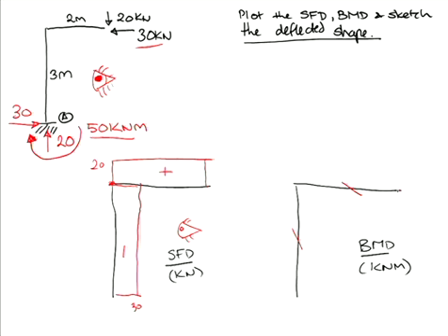So what's the bending moment at the cantilever tip? Everyone, together, 0. What's the bending moment at the fixed support? What's the absolute value there? 50, okay? You know it's equal to the bending moment in the beam. If I now draw a small free body diagram here, I'm saying the moment in my reaction moment is 50 clockwise. So to get equilibrium, the moment in my beam would be an equal and opposite 50.